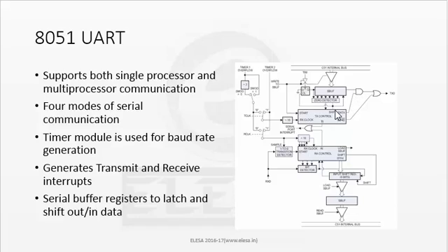Consider the first bit, which is shifted to the right on the first toggling of the shift signal. When the first bit is available at one of the inputs of this AND gate, only when the data bit is 1, the bit under consideration at this AND gate is transferred to this OR gate. Now the significance of the send-ones signal is such that when this signal is 1, the TX line is pulled up to logic high level, and when it is negated, whatever data is to be transmitted is given to the TX line. Every time that a bit is shifted towards the right, a 0 is filled in, since the D flip-flop is having a 0 volt input.